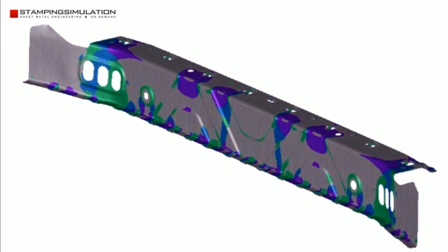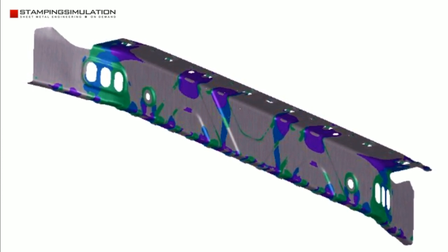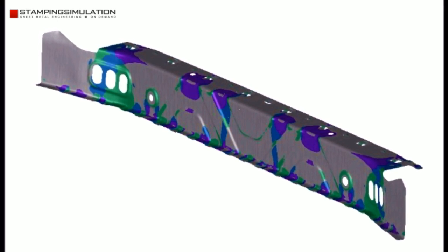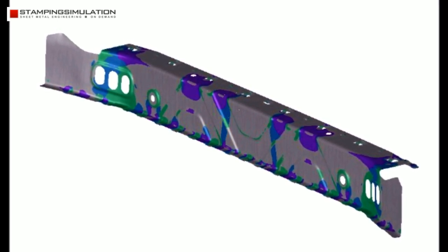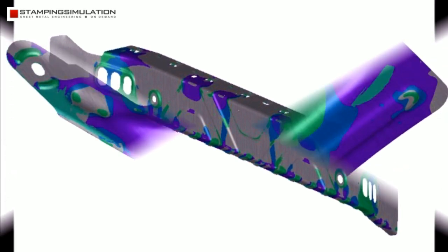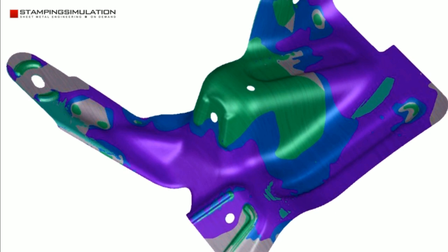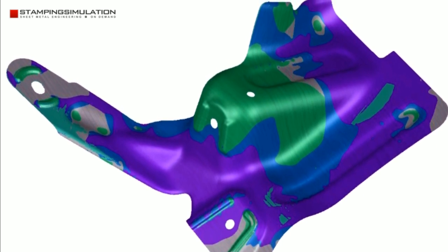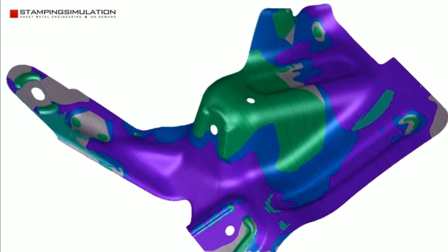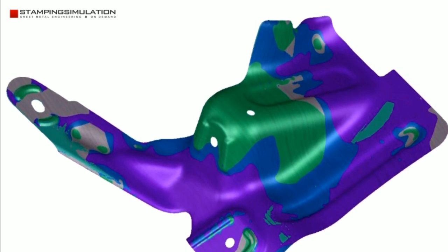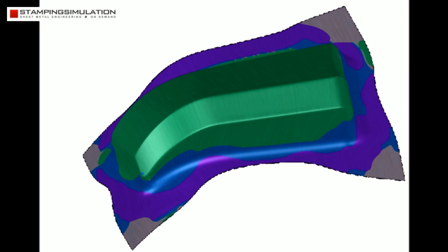Simulation detects any potential problems such as wrinkles or splits in the material, as well as the end strength and material thinning results. Simulation technology can also calculate and compensate for springback, as well as accurately calculate complex trim and blank developments through multiple forming operations. Incremental forming simulation technology, such as AutoForm, always considers the complete 3D geometry of each forming stage and simulates every increment of the forming process.